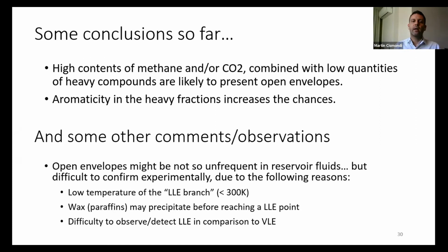Different reasons, and I would choose mainly the following. First of all, as I showed, the liquid-liquid separation part appears at lower temperatures, normally lower than 300 Kelvin, and there are not many experimental studies going to that low temperature range. Second, for some paraffinic fluids, wax may precipitate before you can reach the LLE point, which is the vertical part of the open envelope.